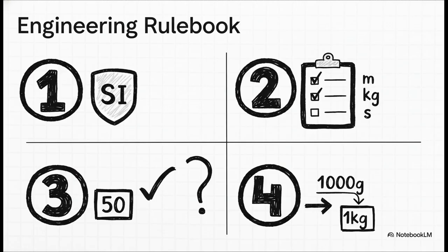Number 1, always use SI units in your calculations. 2, before you even start to solve, make sure every value is in a consistent unit. 3, a number without a unit is totally meaningless, so always state your units. And finally, number 4, use those prefixes to keep your answers clear, concise, and professional.